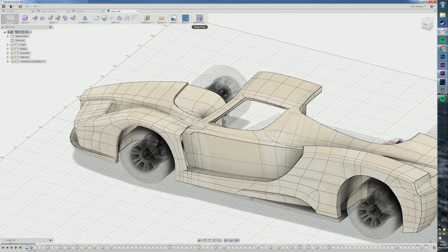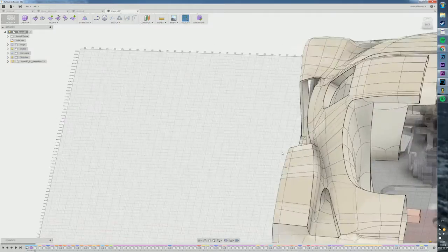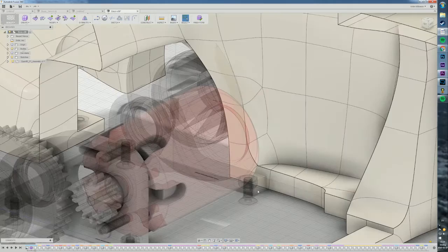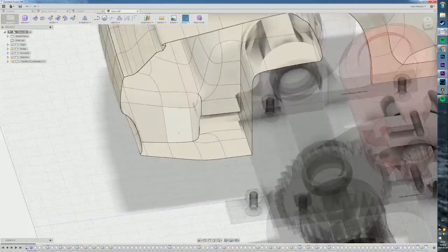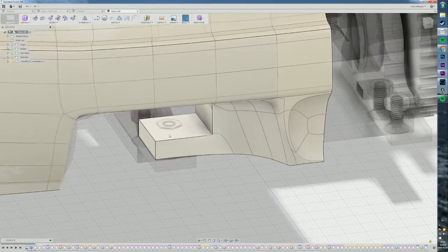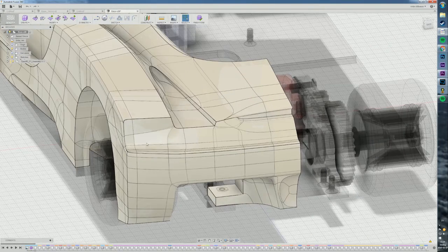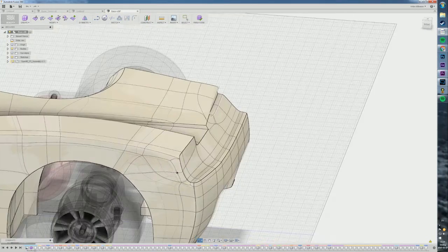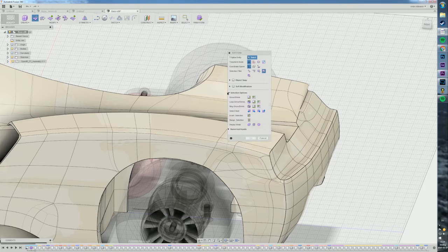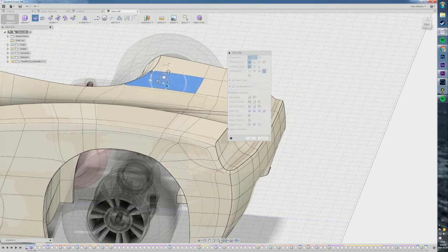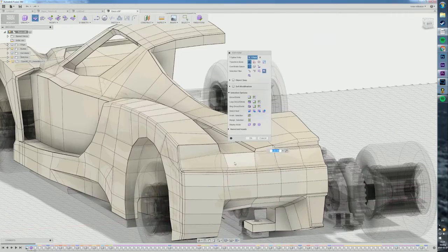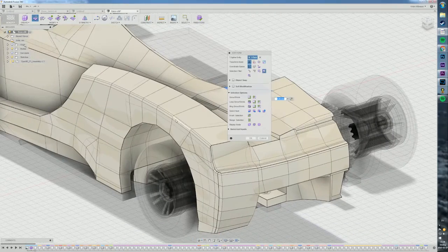When I press this tool, it converts into a solid, and I can then start to cut, add some, let's say here, screw holes for the different screws. Here, back here, for example, I can add holes here for the screws and do that much more controlled. So the idea here is I'm going to show you the tool here. I'm going to edit the tool, go to display mode under selection, and I want to display box instead. Now this is much more unsmoothed. So you can see here how I add details.